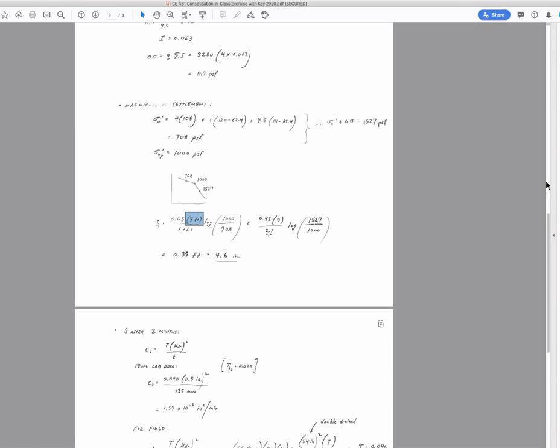The rest falls into place quite readily with 1 plus initial void ratio, 1 plus initial void ratio down here. And in this equation, or in this fraction, I should say, it's always ending point over starting point. And you're just doing it for the first link of that and then for the second link. And this comes out to 4.6 inches.